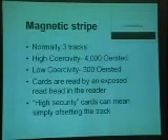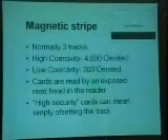And there are certain high security cards. The hotel locks in this hotel are considered by the manufacturer to be high security. Now, you'd be surprised. Basically that means that in general, a regular card reader-writer won't be able to duplicate them. But that can be as easy as adjusting the track offset so the tracks don't line up where they would normally on an ISO standard card. They also use slightly different modulation techniques. So it's by no means high security. It's certainly duplicatable, but just not by your standard card reader-writer.